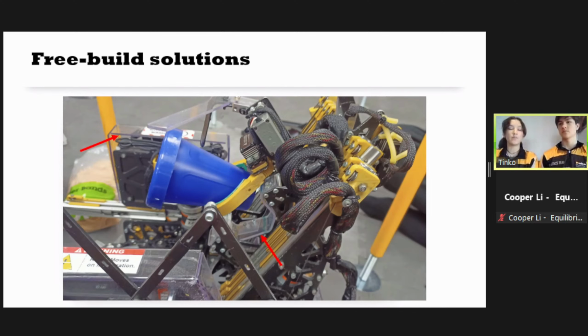And we also have polycarb parts all throughout our robot, just custom bent, so we can never get freight stuck in our robot. We manufacture our polycarb parts just by cutting them up with a handsaw, heating them up with a heat gun, and bending them over any flat surface. So they're really easy to manufacture, and you can prototype them really quickly because of that. For teams that want to use something else or have a lot of COTS parts lying around, obviously the same goes for goBILDA parts or Actobotics parts, whatever you use. So you can just add beams here and there, whatever really works to fix your problem sometimes.